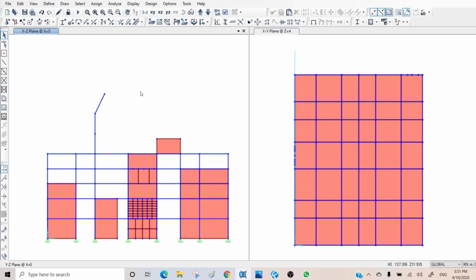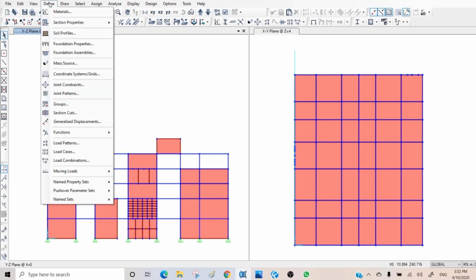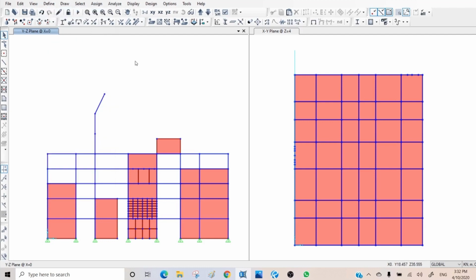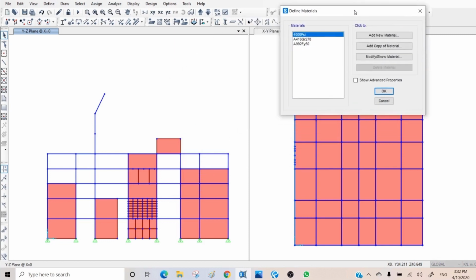Okay, now let's get back to the main subject of this video, which is defining materials and defining sections. For defining materials, I need to come here and choose this Materials, or in the top menu you have the same here if you activated the top menu, Define, Materials. Either way works. So I'm coming here. Currently those are American standard materials, and these two, I think this is different, but here already they are used, so you cannot delete the material.